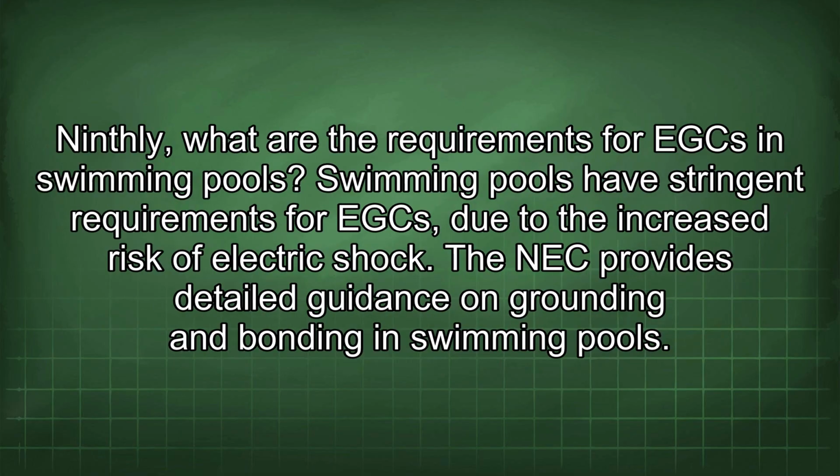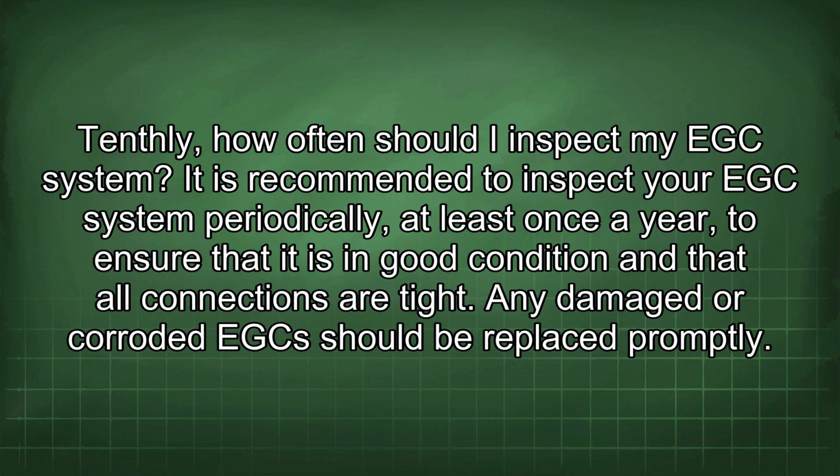Ninthly, what are the requirements for EGC in swimming pools? Swimming pools have stringent requirements for EGC due to the increased risk of electric shock. The NEC provides detailed guidance on grounding and bonding in swimming pools. Tenthly, how often should I inspect my EGC system? It is recommended to inspect your EGC system periodically, at least once a year, to ensure that it is in good condition and that all connections are tight. Any damaged or corroded EGC should be replaced promptly.